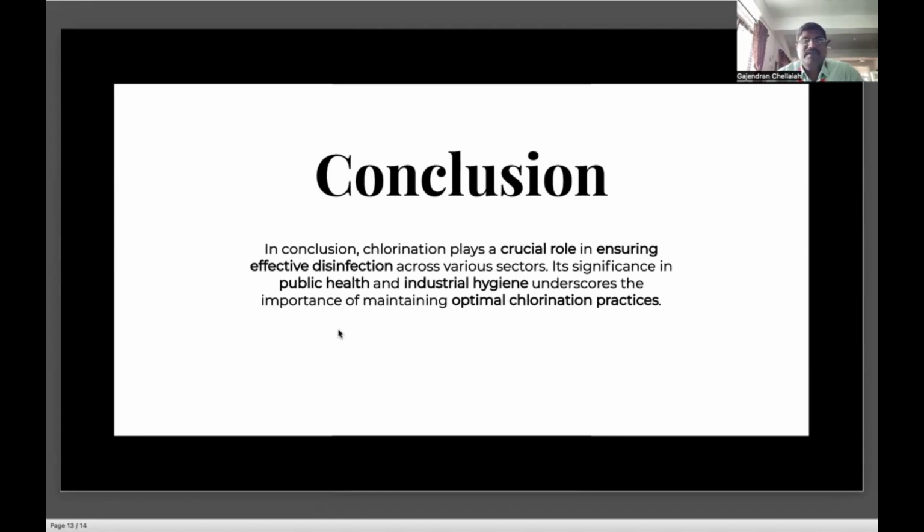It is very important to note how the chlorine system is in place, and still some research and development is going on on how effectively we can use it, because as per the World Health Organization, we are not able to attain the WHO standard for all consumers. Only for a few consumers, on average, are we achieving the amount of chlorine that should be present in the water as residual chlorine. We are not achieving that 100%. For that, some research and development is going on.